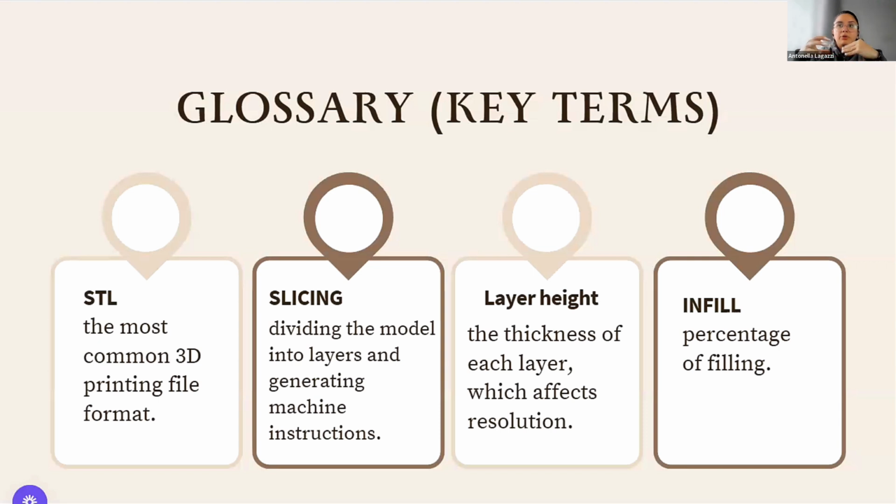So you can prevent some print failures if you visualize correctly in this software that slices the part before printing. Then we have layer height, that is the thickness of each layer.